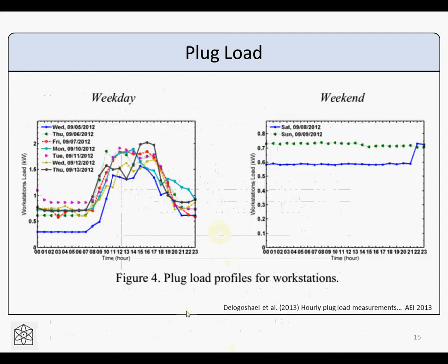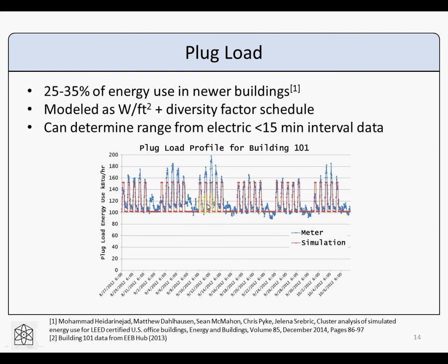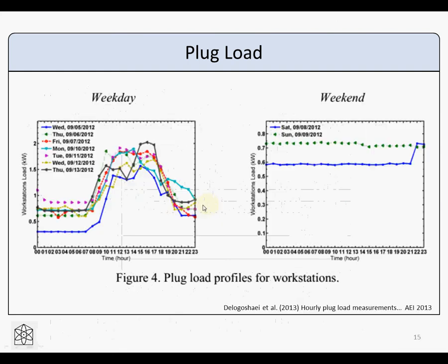This is for an office building in Philadelphia, or you can use some other assumption from the reference buildings that DOE has put together, or from ASHRAE or something like that. This is specific to computers, so for those who have computer labs in your building, this will give you, again, a picture of what is a typical plug load profile that you can expect. And again, it'll be different on weekdays and weekends, so make sure that your templates and your schedules account for that.